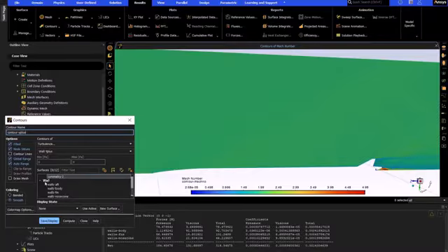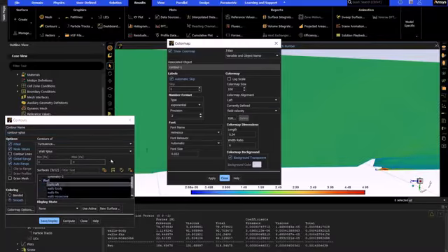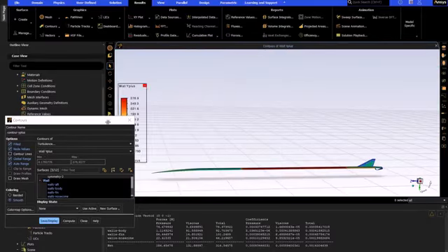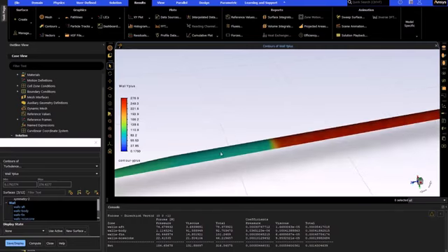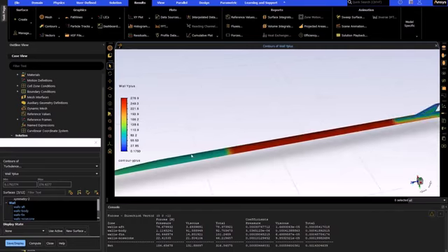Looking at the Y+ contours on wall surfaces shows that the majority of walls have a Y+ between 30 and 300. Zooming in, we can see the Y+ value changes in alignment with the BOI sizing regions, as Y+ is a function of the first cell height.